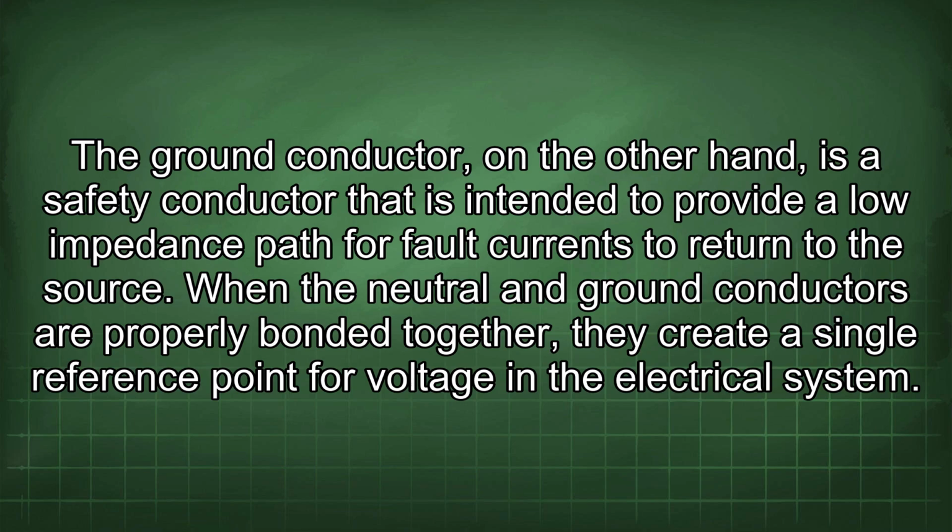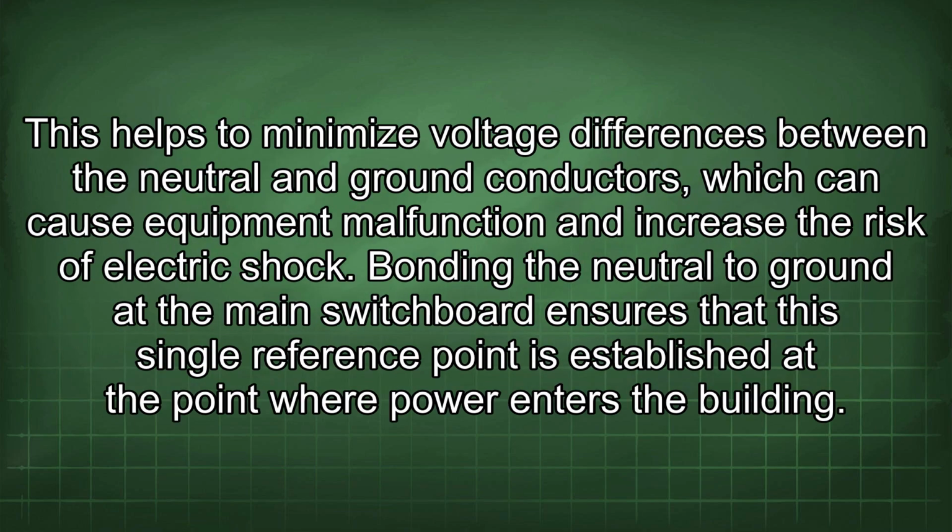When the neutral and ground conductors are properly bonded together, they create a single reference point for voltage in the electrical system. This helps to minimize voltage differences between the neutral and ground conductors, which can cause equipment malfunction and increase the risk of electric shock.